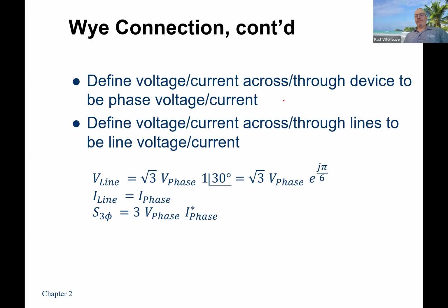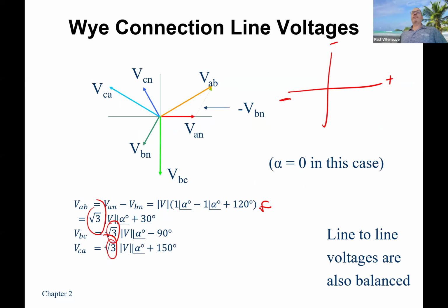Let's say you have a three-phase wire and want to measure the angle of the voltages, to find the angle between them and which one is zero. There is a device called an oscilloscope, and you can use it to look at the waveforms. You can also have a phasor analyzer that can do it, but you have to pick a reference phasor. One has to be your zero angle, and the others are based off that. But the easiest way to do it is an oscilloscope.